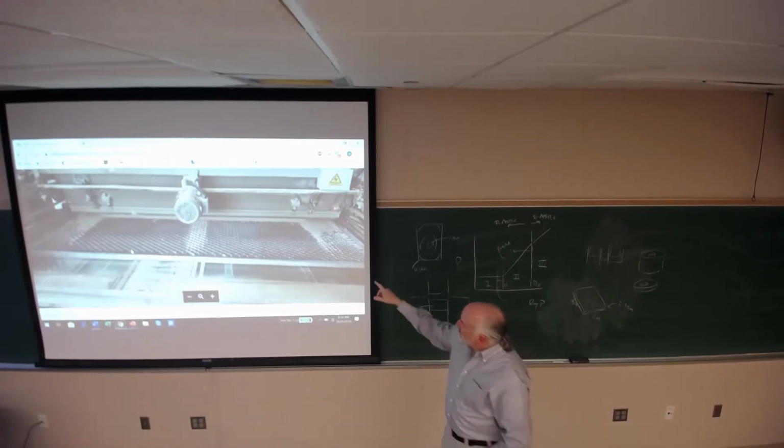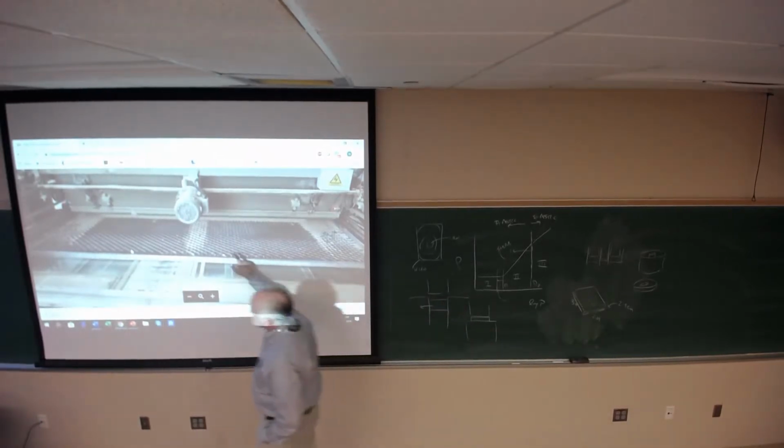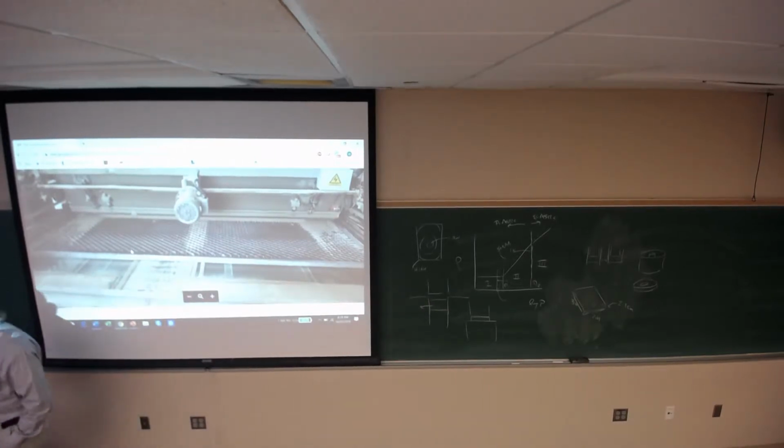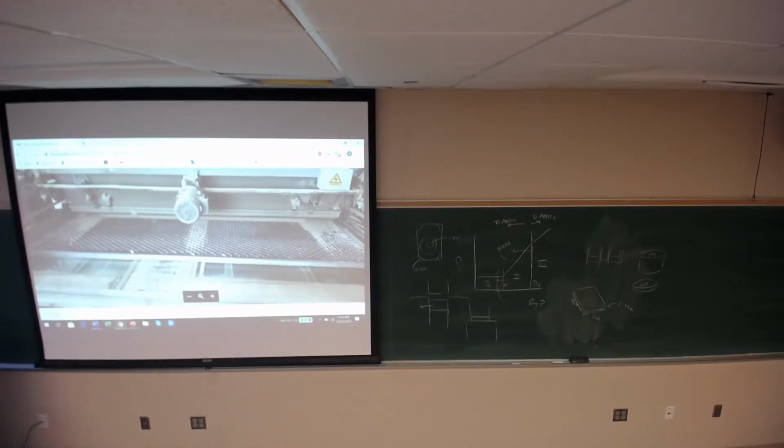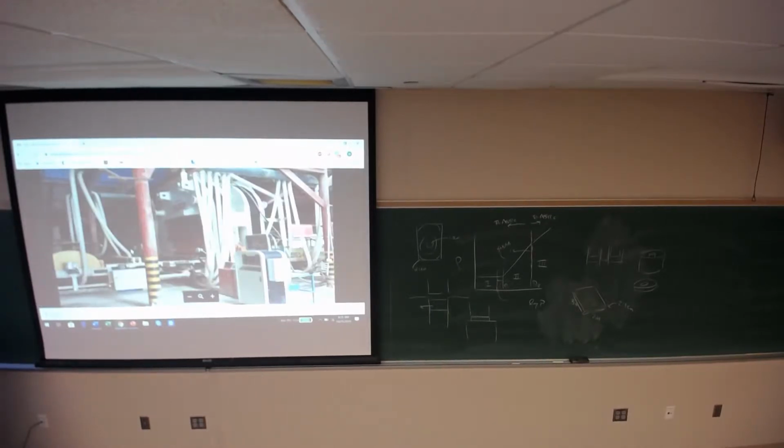But this die fill is great because you get very uniform die fill, and that is the key to dry pressing. In academia, we don't pay any attention to that because how are you going to navigate or measure variations in die fill on a small volume? You can't do it. We're not equipped to start doing pounds of material. We're really good at the gram level. We're not really good at the pound level.